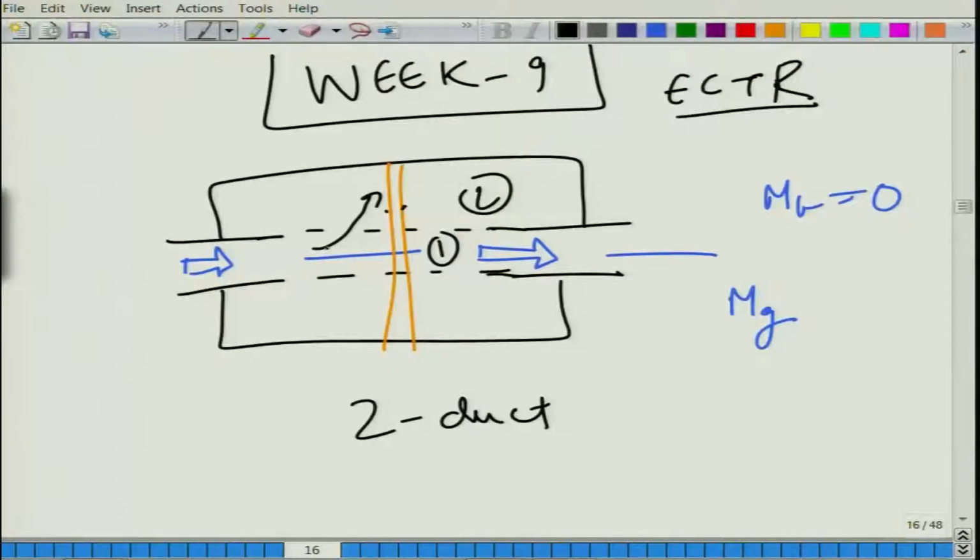Another thing that I want to tell you is that we are assuming the grazing flow in a straight through duct to be constant throughout, but it will never be constant. The grazing flow will tend to decrease, and a little bit of non-zero flow will be there across the perforated element, even in a straight through muffler, that is a 2 interacting duct muffler.